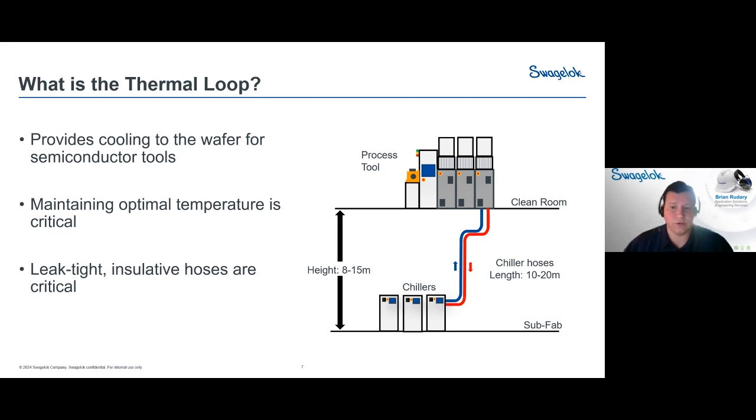Use of different solutions that are properly insulated and leak tight allows for consistent and more repeatable performance across the manufacturing space. Maintaining thermal consistency is going to result directly in the output of that manufacturing tool. Any excessive temperature variations can increase scrap and downtime, with the consequence of failure potentially being in the millions of dollars for subtle variations in temperature, so a lot to risk.